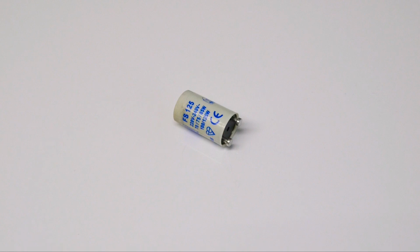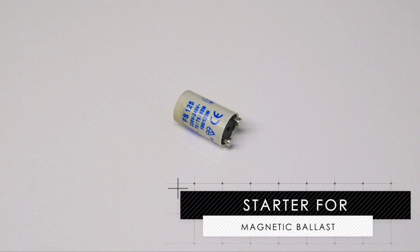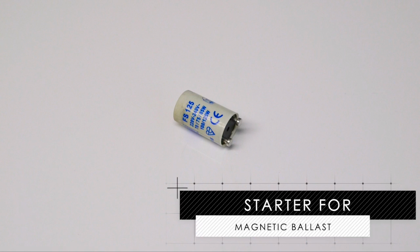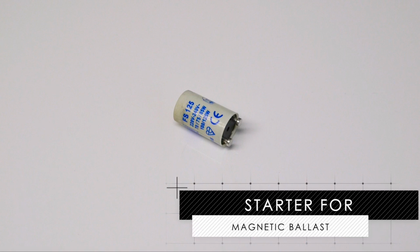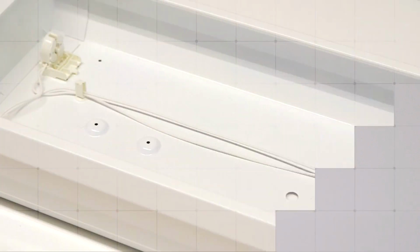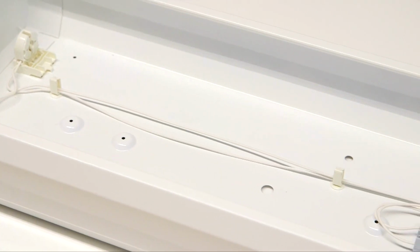There are 2 main types of tube fitting, one with magnetic ballasts and the other with electronic ballasts. You can differentiate between the 2 types quite easily. A fitting with a starter, shown here, has magnetic ballasts, and a fitting without a starter has electronic ballasts. This fitting is a standard 5-foot version designed to take 2 tubes. As you can see from the lack of a starter, this product is fitted with an electronic ballast.